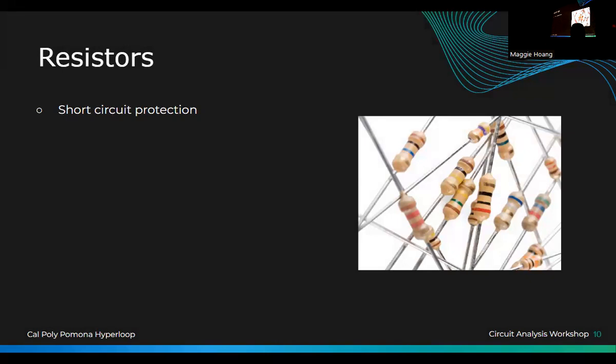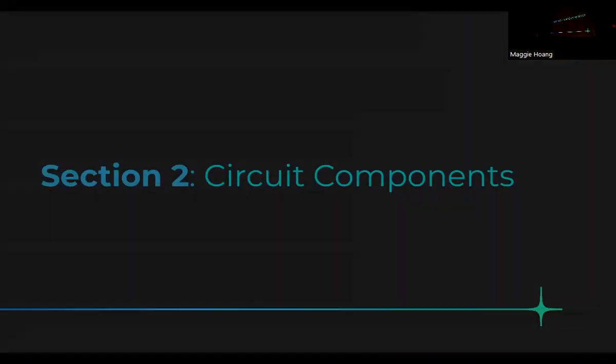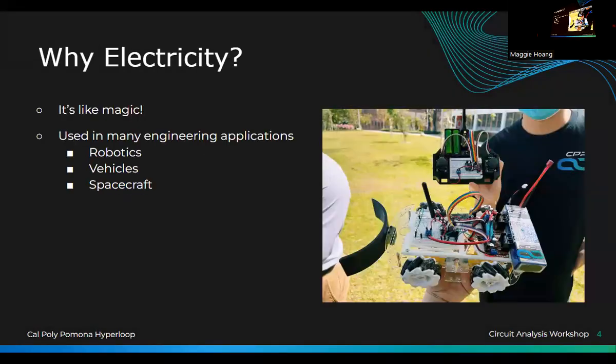So when you have a battery, let's say, does everyone know what a LiPo battery is? No? Okay, for those who don't know, this right here is a LiPo battery. It's very powerful and the discharge rate is very high. When you use these LiPo batteries, you have to be very careful. Short circuiting is when you put the positive and the negative together without any load or resistance, meaning 100% of that current is going back together, like it's in the same loop.